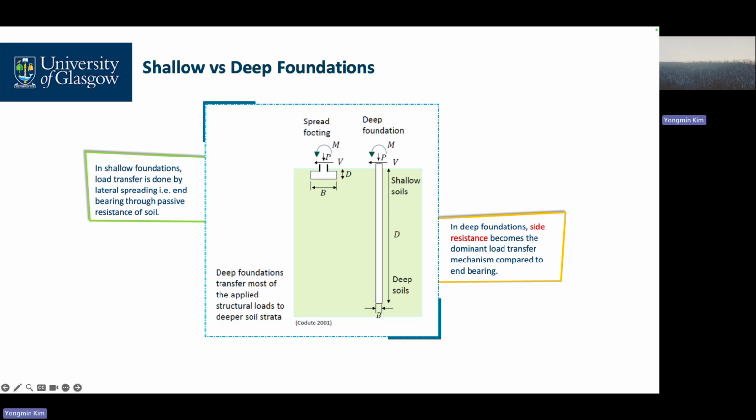In the shallow foundation bearing capacity, cNc: c means cohesion. qNq means embedded depth effects, the confining effects. 0.5 gamma B N gamma means width effects. The combination of these three gives our shallow foundation bearing capacity.